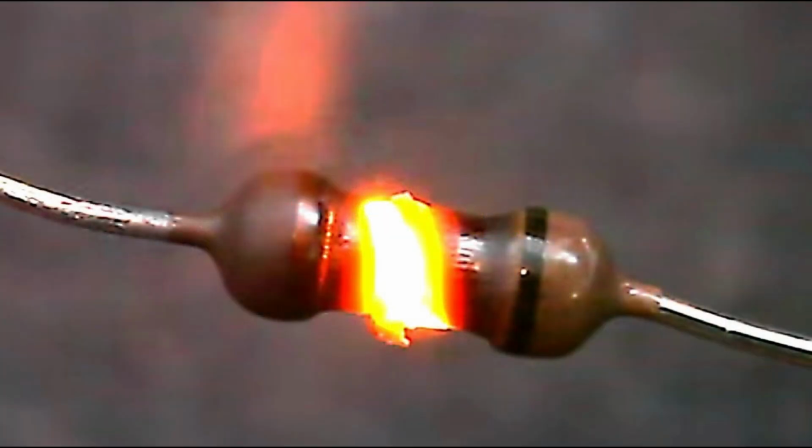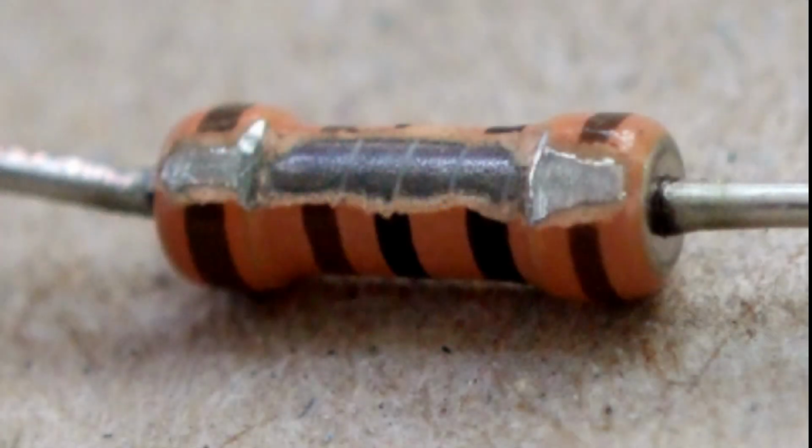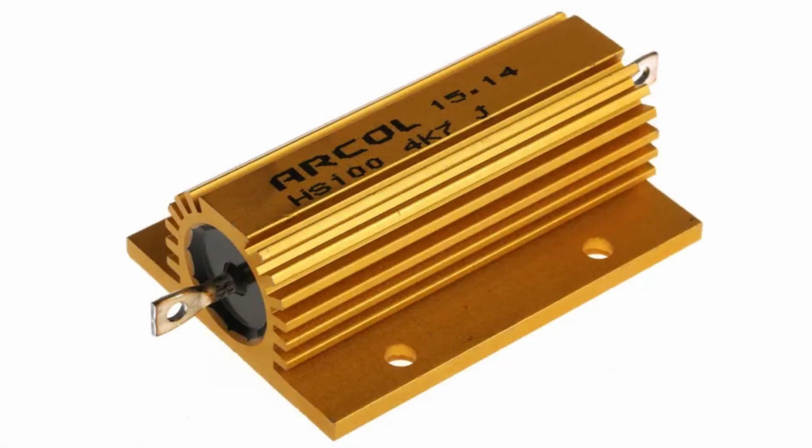Metal film resistors have much better temperature stability than their carbon equivalents, lower noise, and are generally better for high-frequency or radio-frequency applications. Metal oxide resistors have better high-surge current capability with a much higher temperature rating than the equivalent metal film resistors.